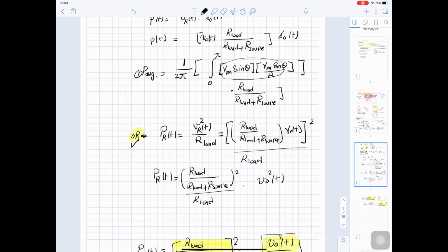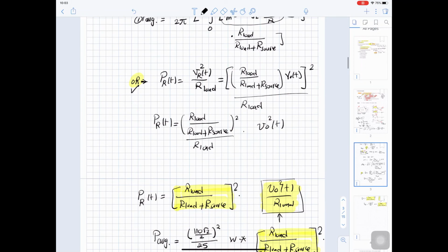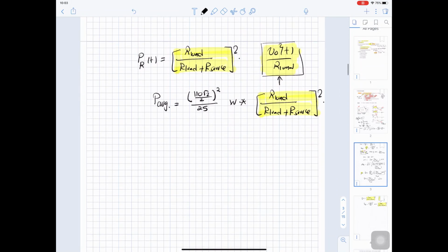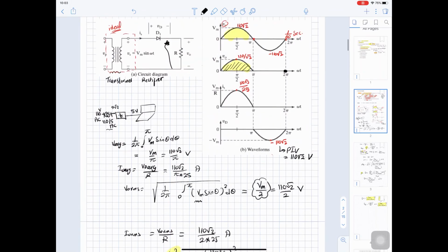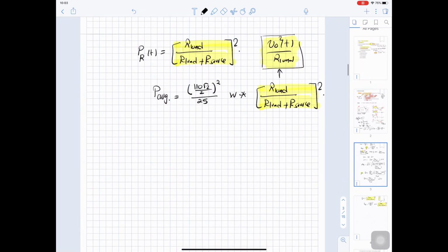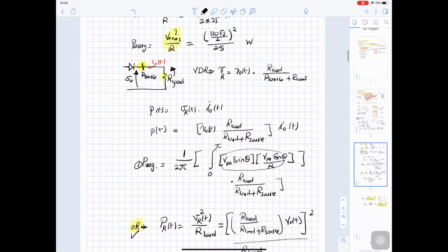These are little tricks that can be added to a typical power electronics question. Here we just mentioned that there is a resistance added for the source, and in this case the voltage across the resistance is not V out, so you have to use a voltage divider.